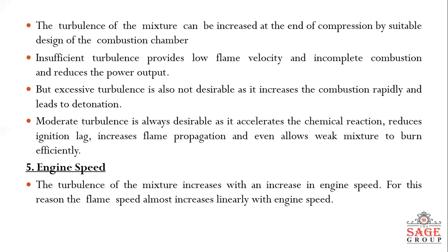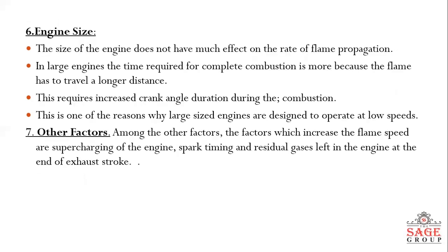A suitable design of the combustion chamber, which involves geometry of cylinder head and piston, may increase the turbulence to a desired amount during the compression stroke. Next is engine speed. The flame speed increases almost linearly with engine speed, since the increase in engine speed increases the amount of turbulence inside the cylinder. So the time required for the flame to traverse the combustion space would be halved if the engine speed is doubled.